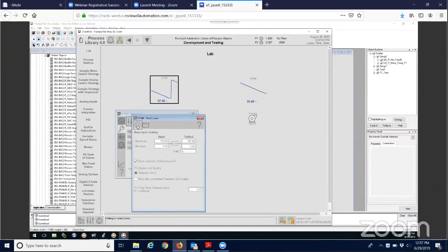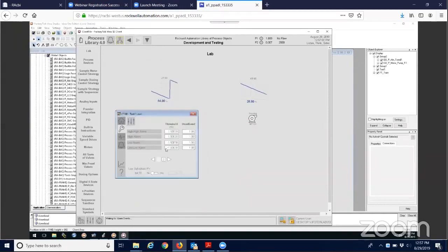But while it didn't take them very long to put it on the screen, now changing all the little minute details that you usually have to deal with, if you did it in Application Code Manager or you did it ahead of time, you can do all of these edits at the controller level. You don't necessarily have to do it at the HMI, but the goal of all of this is once you're in the HMI, you shouldn't have to open up Studio 5000 to be able to commission your system. And that's kind of the goal of this. And correct me if I'm wrong, Application Code Manager, you can set a lot of these parameters too in a bulk level. So this is kind of the slow way of doing it, but it's still not that bad of a way. Okay, so you can see now I've got my labels and stuff going.